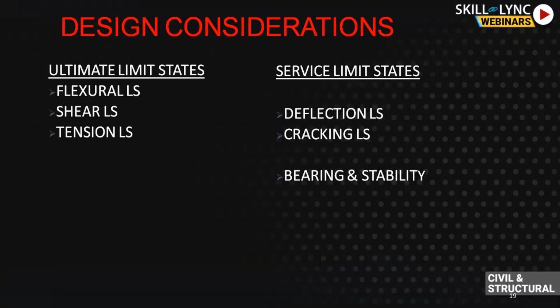Apart from all this planning, like typical buildings, we have flexure, shear, and tension limit states. But where the structure governs in design in environmental structures is serviceability. Most important and crucial of them is cracking. We have bearing also, sometimes it can overturn also, but the most important, which is the stringent criteria, is cracking.